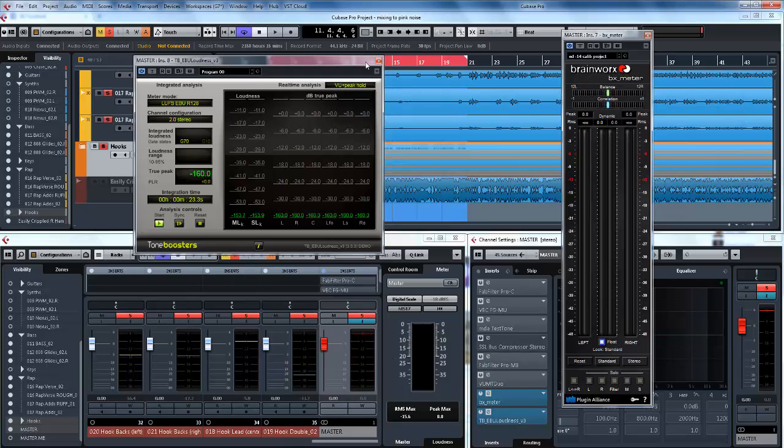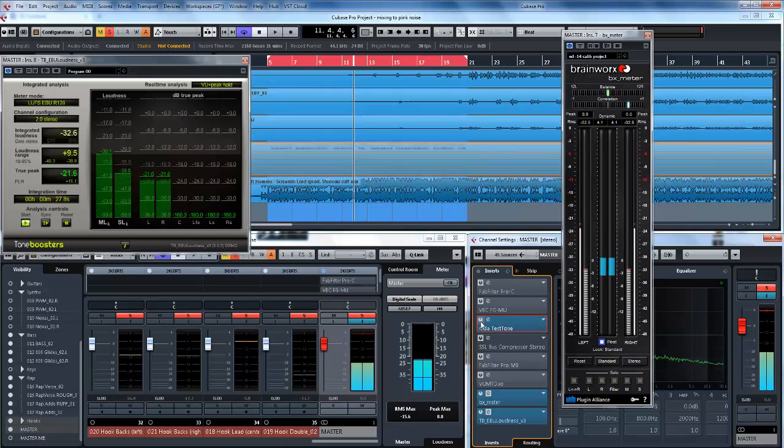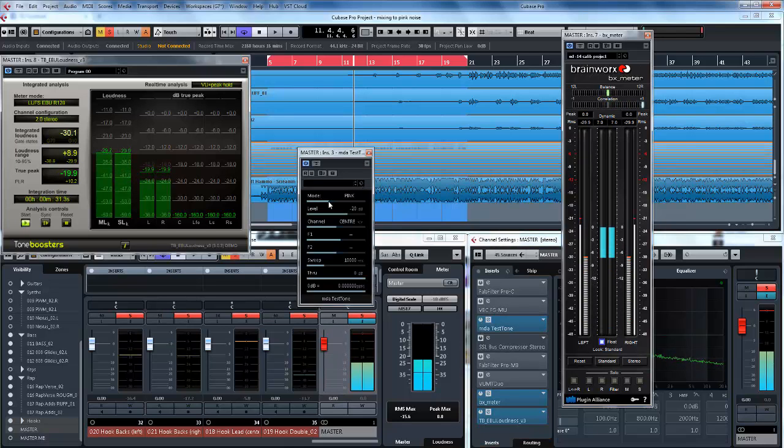And to do that, instead of running all the audio, let's run the test tone and put it on sine. Okay, and now we can test to make sure we get all the right values everywhere. What I want you to look at is -20 here. This should say -23, and you know that if I flick this switch in, that should drop down to -20. There. So we've calibrated these two to 0, -20, -20.